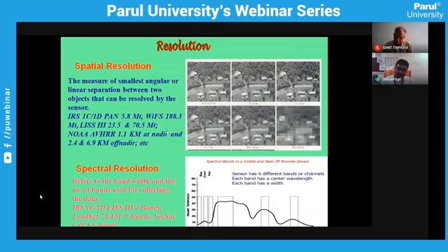For the time being, I am just giving some examples. Now we have Cartosat 2, IRS P6. It has a pan image of 5.8 meter. Five point eight meter resolution means whatever object is more than 5.8 meter, you will be able to distinguish from these images. If it is less than 5.8, we can't distinguish. Nowadays, people are using LISS 3, which has a resolution of 2.5 meter, or you can say almost 6 meter resolution we can get. So these are very advanced things happening. Sensors have now evolved to be more efficient to cover the area.